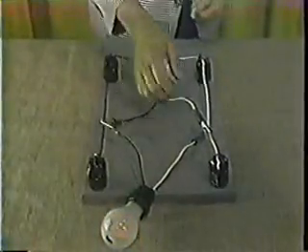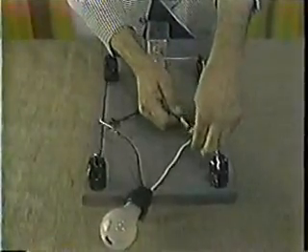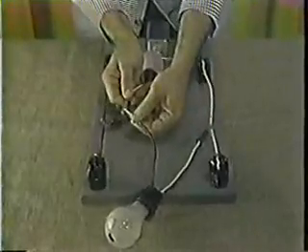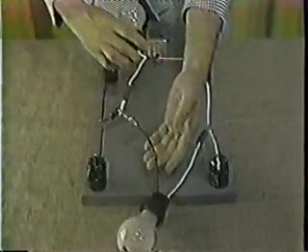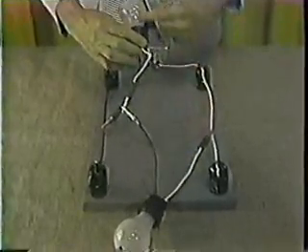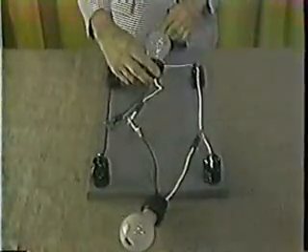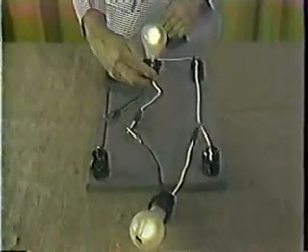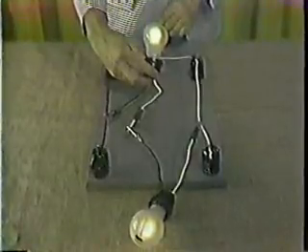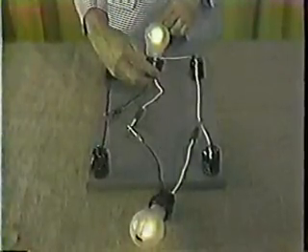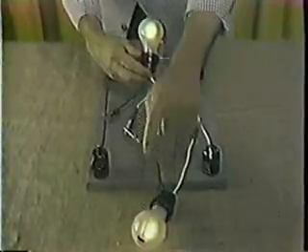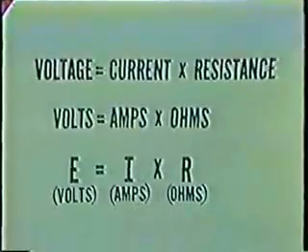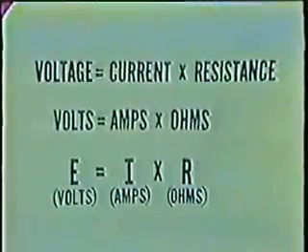This is what is known as parallel circuits. Most wiring is done using parallel circuits. If we take the 2 bulbs and connect them like this, they are in what is known as a series connection. And as you see, they won't burn as bright as before. This is because we now have doubled the resistance in the line, which in turn has cut the amperage in half. We could have predicted this would happen from Ohm's law.